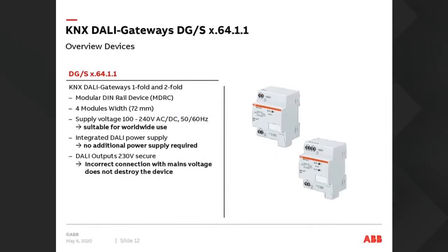Some more specifications on the device. It's a DIN rail device, mountable on and off the DIN rail without a tool. It's spring loaded, you don't have to do anything. It's 4 modules wide, so it's quite neat and small compared to some other systems where you need an individual DALI power supply. With this device, you don't.